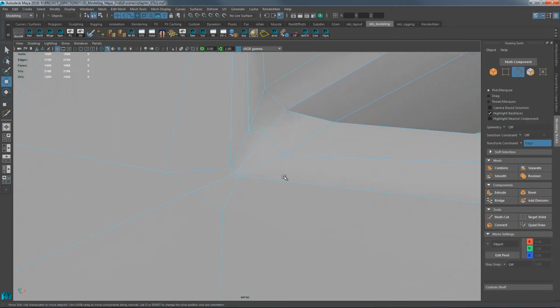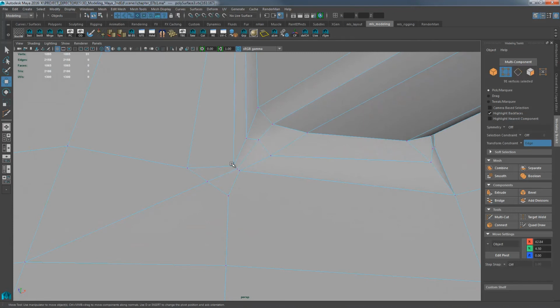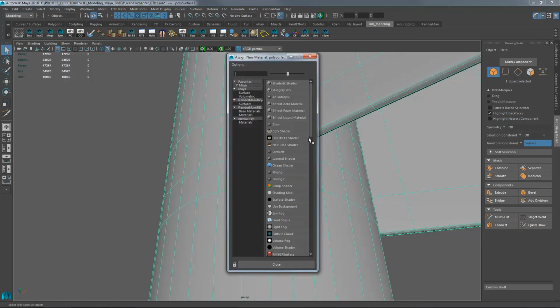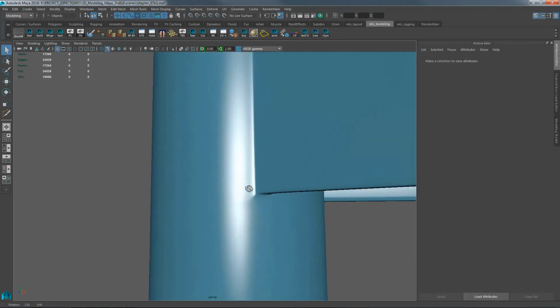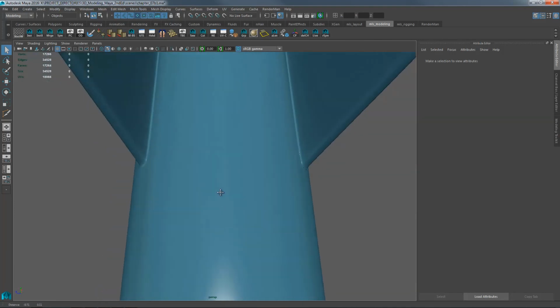And now we should have 1, 2, 3, 4, 1, 2, 3, 4, so on, count it. But take a look at it. Do a little edge sliding, get things out of the way, clean it up. Looks really good. Maybe surface sliding. Try to do minimal vertex moving, otherwise it'll hurt the precision manufactured look of it. I'm just going to toss some material on it so I can study that specular highlight and see how I did. Yep, not too bad. Not too bad. Really not noticeable. Now I can fix the others.